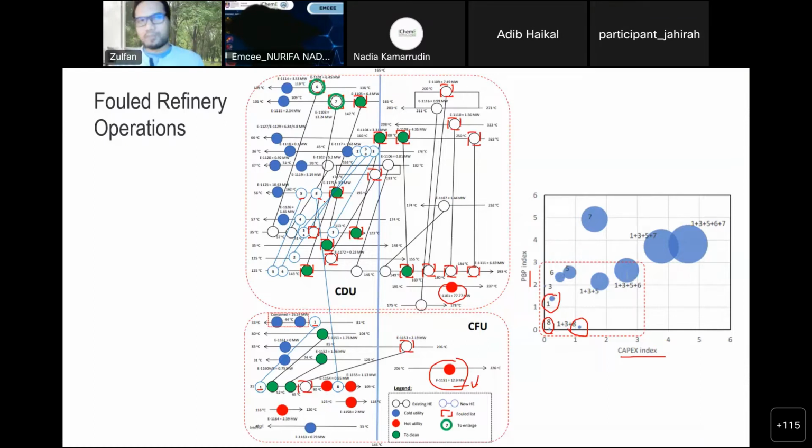For example, if I put this in a high platform, that means we need to ask the civil or structural engineer whether that platform can withstand this additional new exchanger. And we also need to look on the field whether the maintenance people can take out the bundle so that they can do maintenance on this particular heat exchanger. So these two aspects are things that we cannot easily quantify when we do, like I said, the theoretical delta T min versus the capital cost graph.